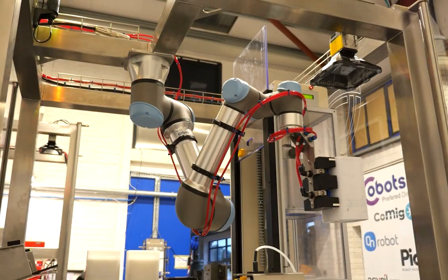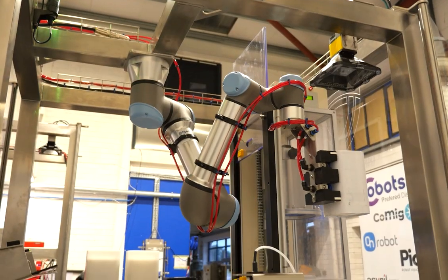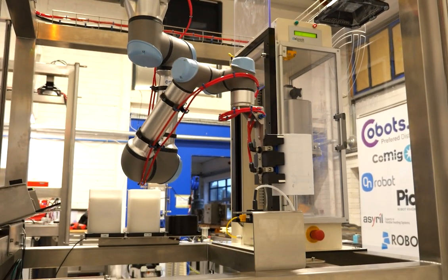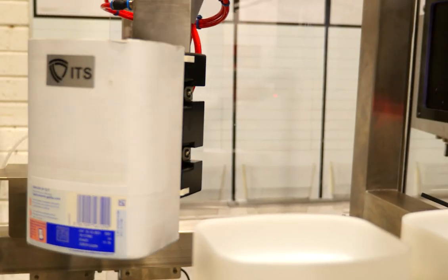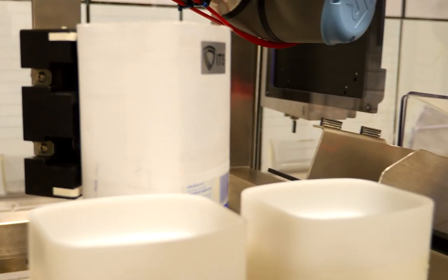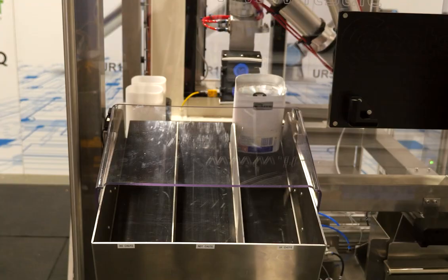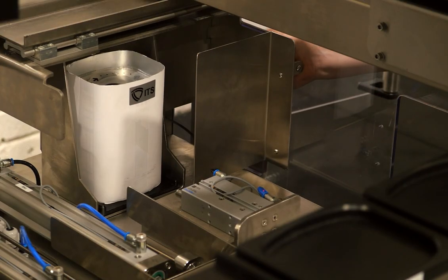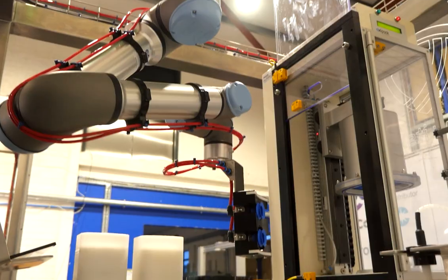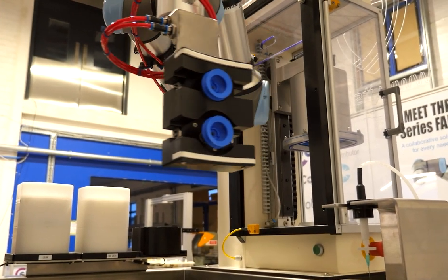where it will test the integrity of the foil seal on the top of the canister. And based on that output, it can say whether a part's a pass or a fail. Now, this closed loop testing means that there is no human error in the complete testing regime. The robot is responsible for each step. The custom gripper on the end has a vacuum cup that can connect to the outside of the canister and hold it with enough force so that it holds it steady whilst it's reading the barcode.